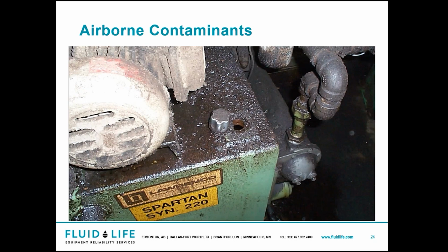This one here is always a good little story that I like to tell. So this here, Spartan 220, it's a thicker oil, right? And the technician in this picture here, he had punched out the filter screen on the tank because he said it was easier to pour oil. I'm like, clearly you did a good job of pouring because it's all over the components and on the ground. But he was using those galvanized buckets. So for those of you who are using those galvanized buckets, please don't. They're awful. They're full of contaminants. You're better off using a funnel.